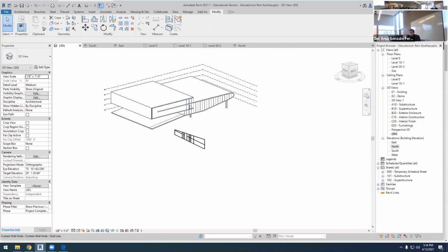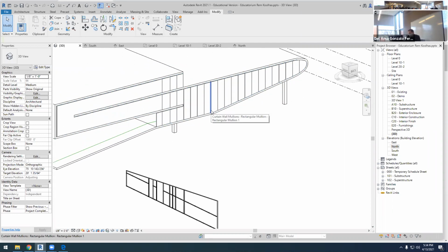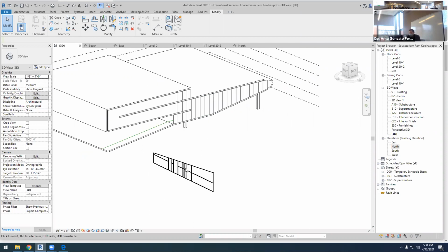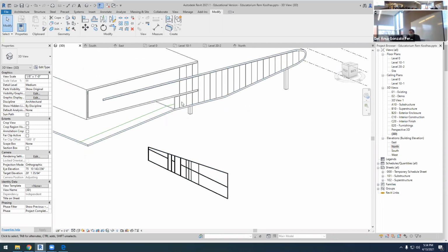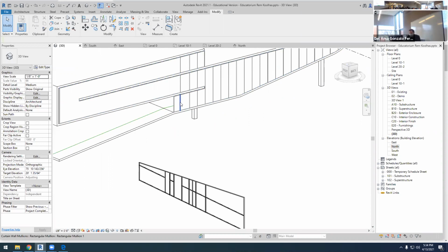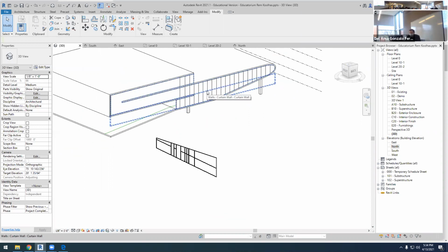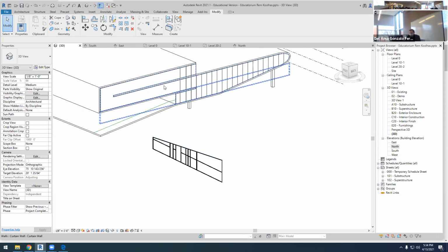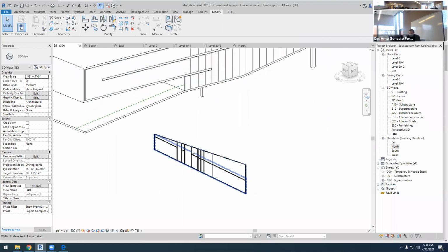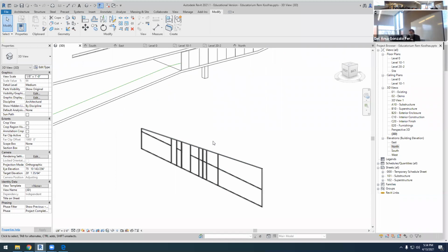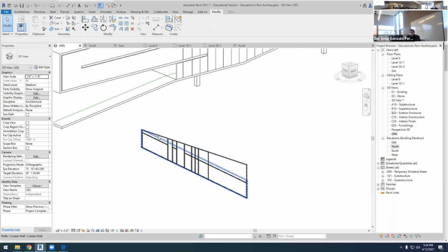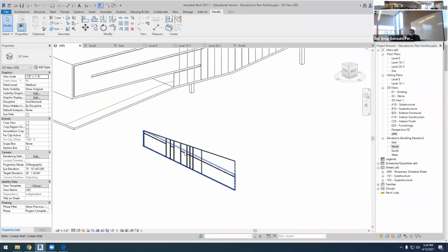Okay, so today we have been working with curtain walls. I think it's worth it, especially if you can create your own design. So do not use the storefront when you want to cover a large area with glass. Do not use just glass. Try to design your own curtain wall, and then your building or your design will be something unique. And don't go crazy with patterns.